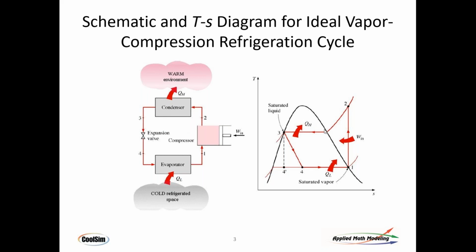Once you get to the point where the air, or the medium, has cooled enough, then you drop to an expansion cycle. You go through an expansion valve, and that drops the temperature down because, again, PV is RT. The ideal gas law says that if you drop the pressure, temperature is going to drop with it. This chart is an ideal state here. There is some entropy growth, so it's not ideal. This number 4 and 4 prime, the difference between those two is entropy growth caused by inefficiency of that process. It's not perfect. And then you absorb heat.